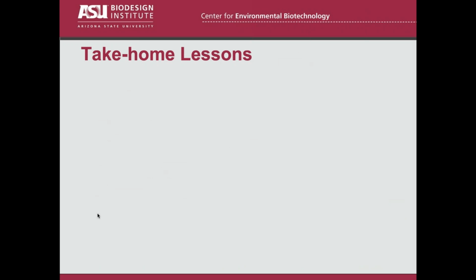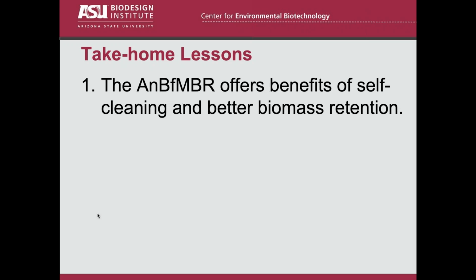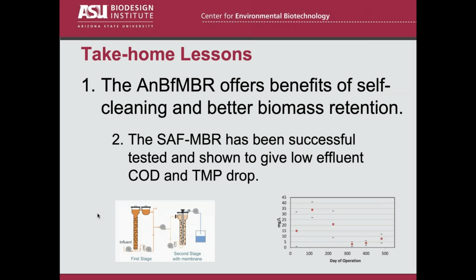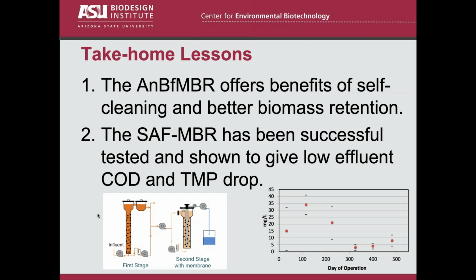All right, now I'm coming to near the home stretch here. So let me just review the take-home lessons on this. One, the anaerobic biofilm MBR offers huge benefits in self-cleaning and better biomass retention, better process stability and performance. The SAF MBR has been extensively tested around the world.